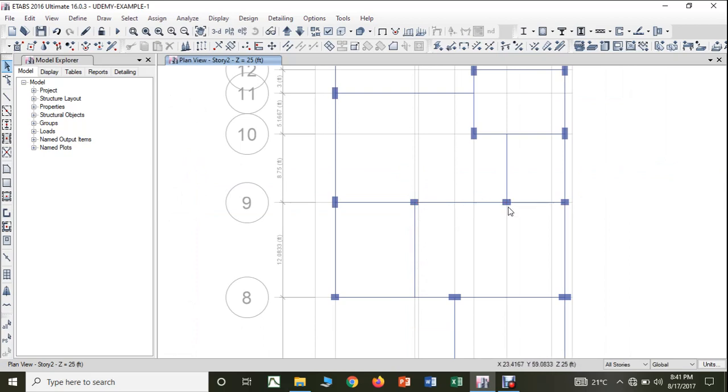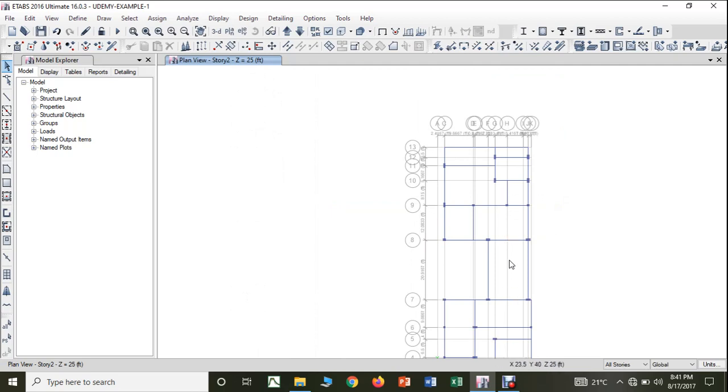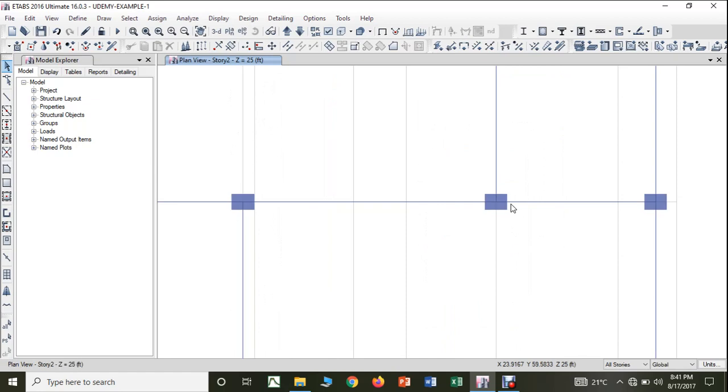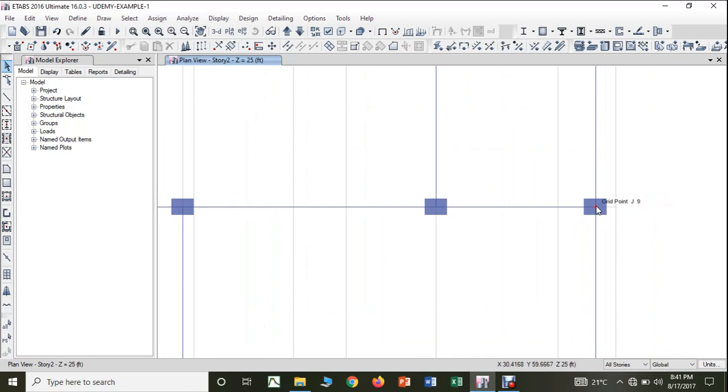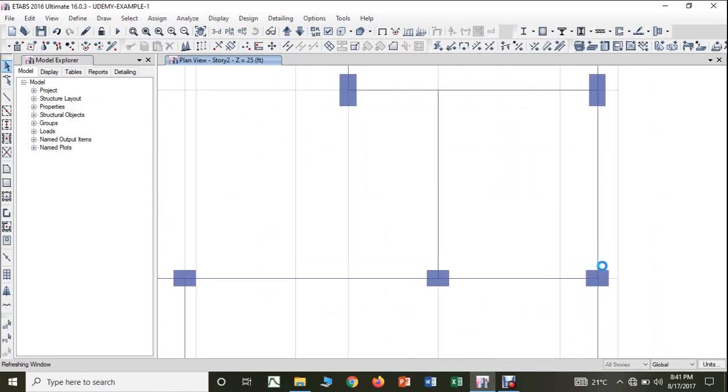Then what about this column orientation? That column orientation is also nice because this is main beam, this is also main beam, all are in continuation with this, so therefore no need to change. If you want you can change it to this direction, but it will create an eccentricity here. So therefore we will rotate and we will keep like this.